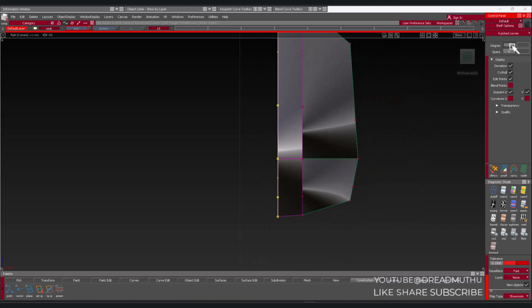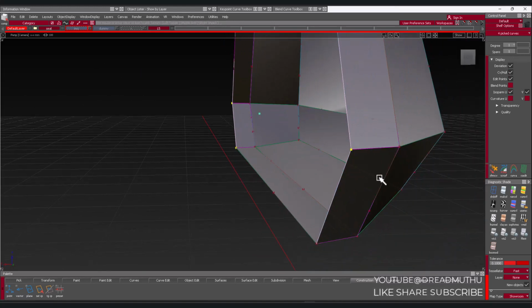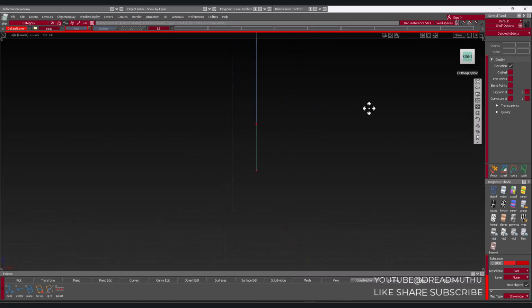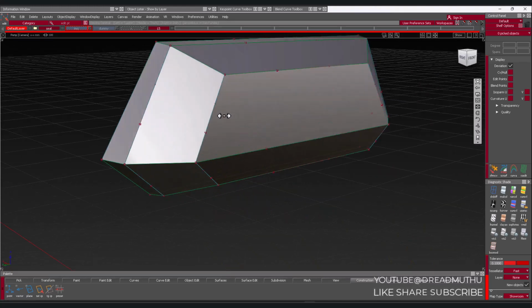So I'll make it 1 and 1 so that it will be easy for modifying the shape. I'll select these curves, hide and select. I'll make it align so that if I move this CV, the other CV also moves with it. Yeah. Okay.